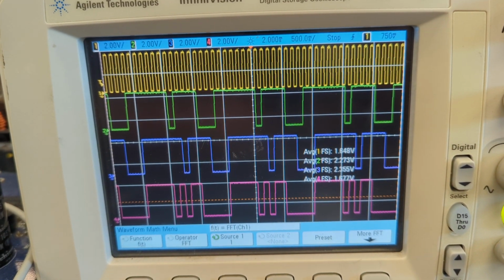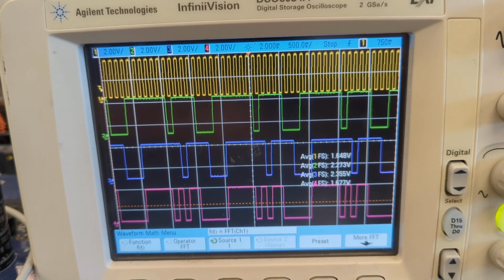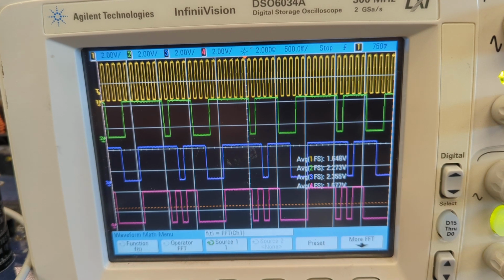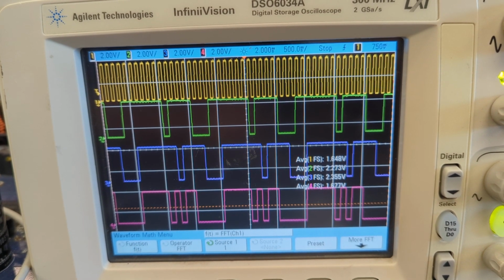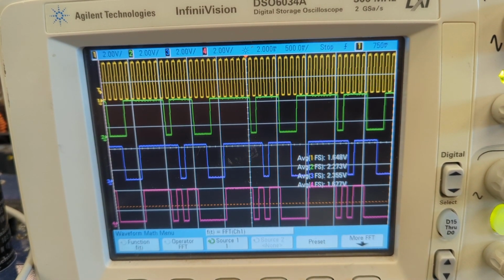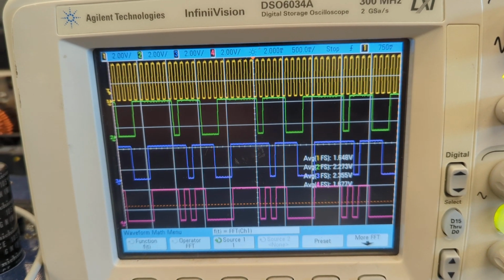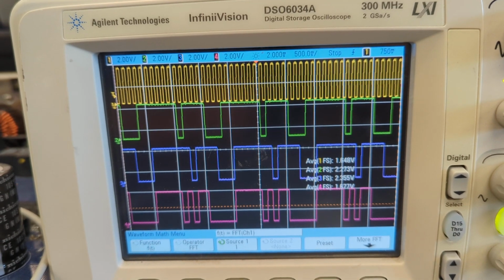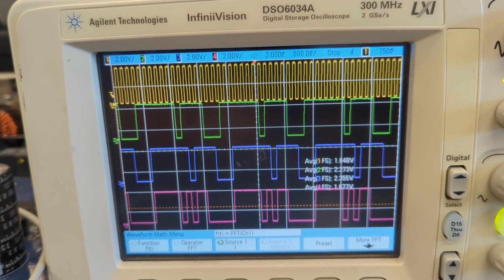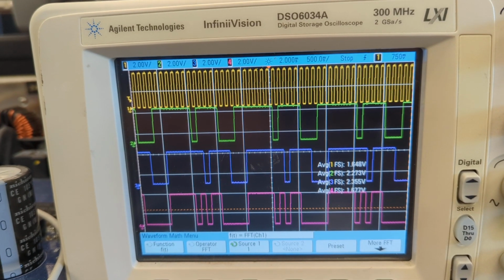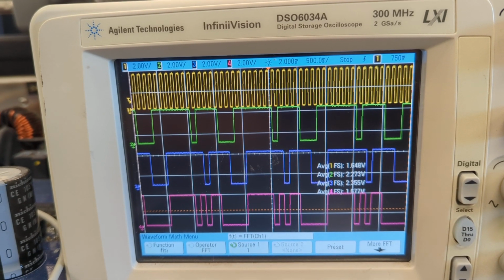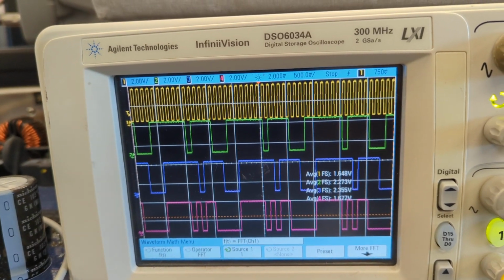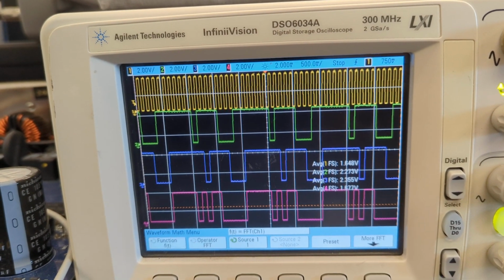How do we do that? Well, we'll take a binary weighted digit and convert that to a randomly generated series of digits. For example, if I have the number 1 on a 2-bit number, I need 4 clock cycles to show that 1. As long as there's one 1 every 4, it doesn't matter which position, right? I have a probability of a 1 being a 4th.